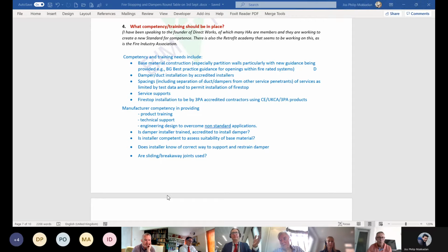Where's it going to end up? You're going to end up with services designs which are drawn to technical design at Stage 4A, which don't take due account of deflection heads and spacings in walls, because that's a specialist function of CDP from a drywall company, a damper supplier, or a fire rated and smoke control company. The horse has bolted, it will not fit. That's where you kind of sit.